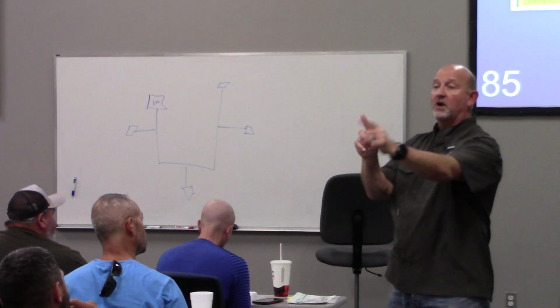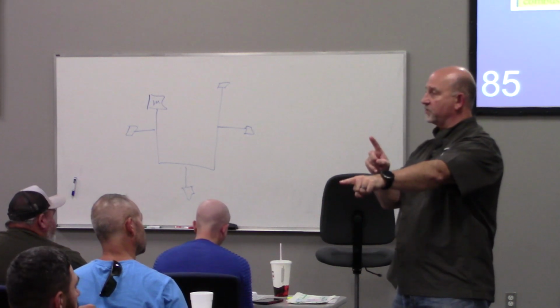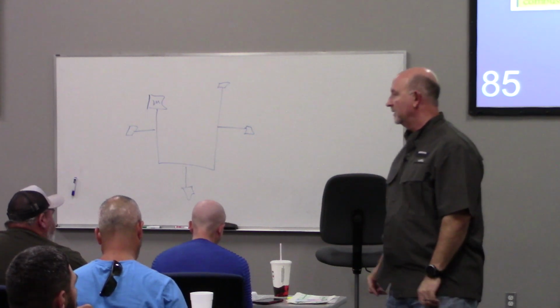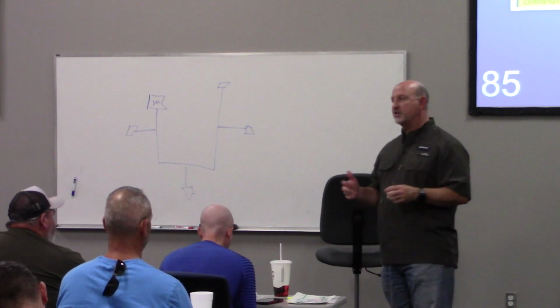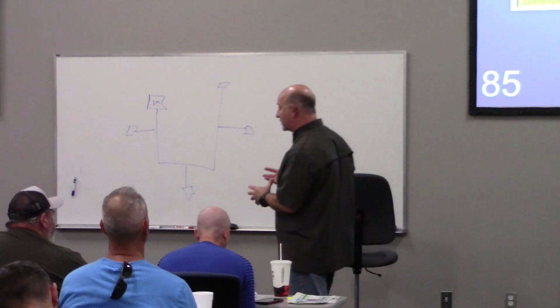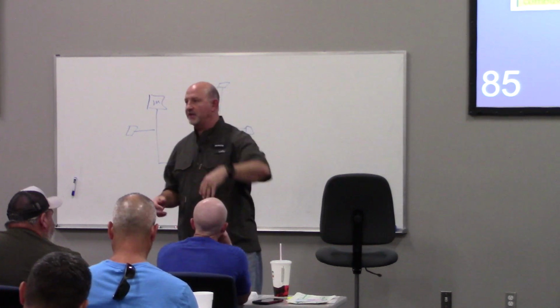So, look at me. Do you agree one guy is indoor opening, one guy is outdoor opening? Do you agree I would never ever talk to both of those guys? I'm either going to give you an indoor opening, I'm going to follow his rules, or I'm going to give you an outdoor opening and I'm going to follow his rules. I'll never listen to both of them. Again, this is why I give these guys a different name and point them out, because we still have a tendency to read 701.4 and 701.5 and 701.6 when really only one of those are the rules we need to comply with.